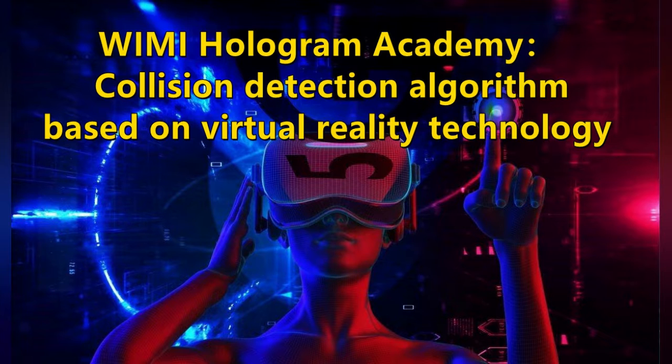The axis-aligned surround box AABB is the first class of surround boxes and the most widely used in collision detection studies. The AABB of a model is defined as the minimum rectangular hexahedron containing the object with edges parallel to the coordinate axes. For a given object, its AABB requires only 6 scalar descriptions, namely the maximum and minimum x, y, and z coordinates of the vertices of the basic elements constituting the model.